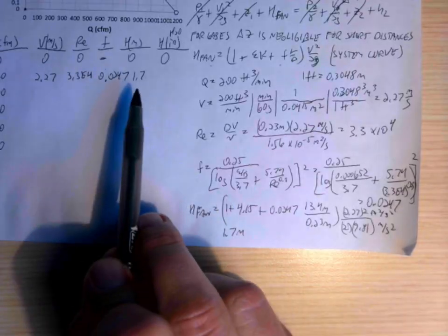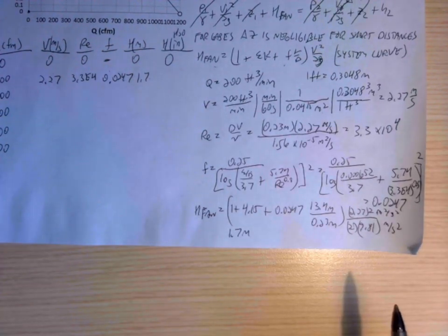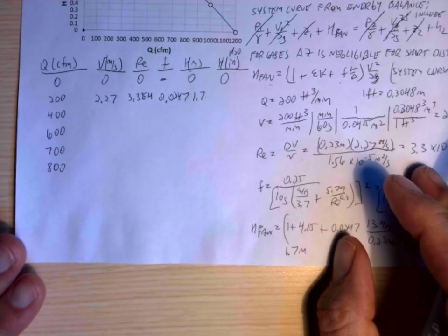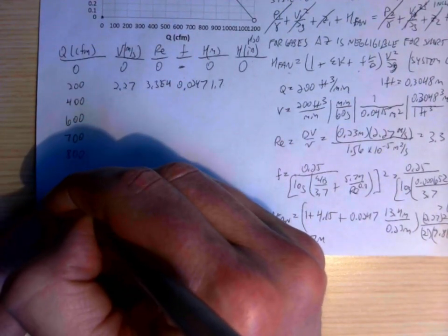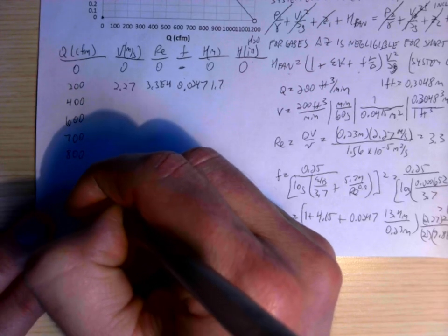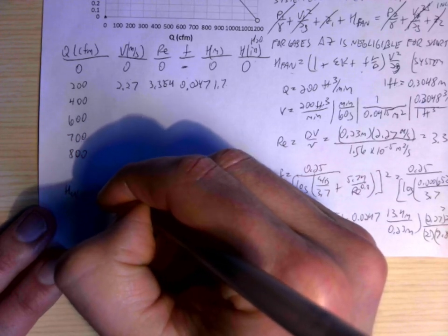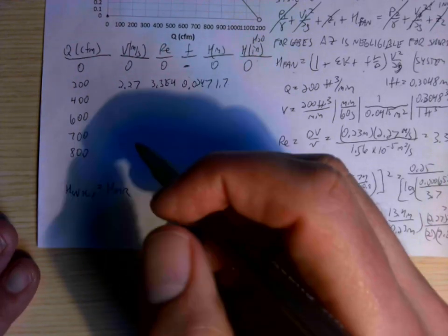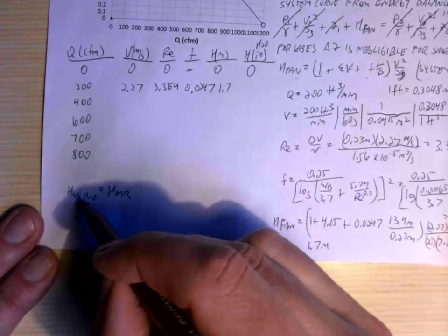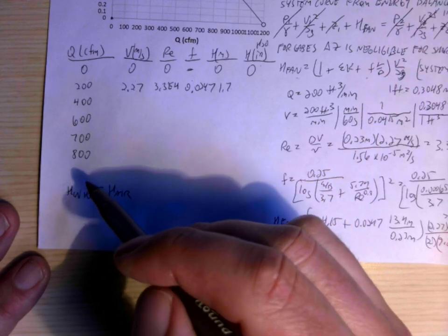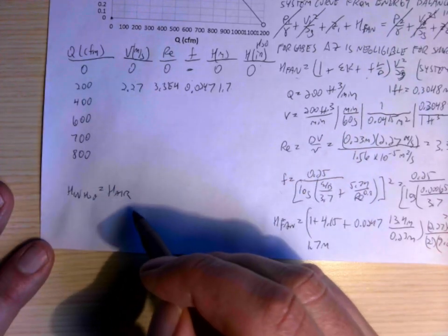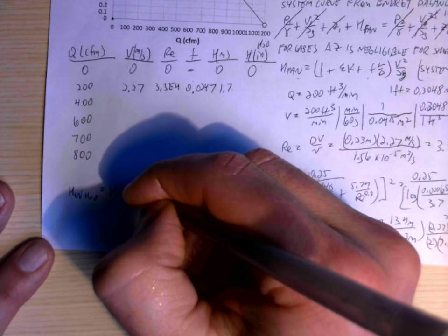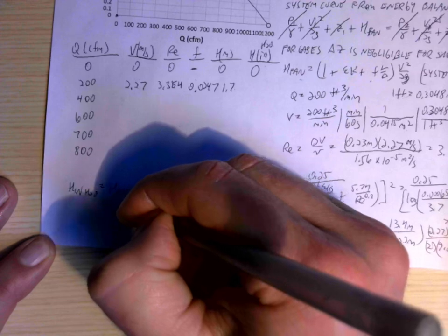So we got 1.7 there for the meters of air, and we need to lastly convert this to inches of water. So H in inches of H2O is going to be equal to H air, and the way to do that conversion is to just multiply by the density. So H water times rho water should equal H air times rho air to have the same relative change. Okay, so that means that I just multiply this rho air over rho water,